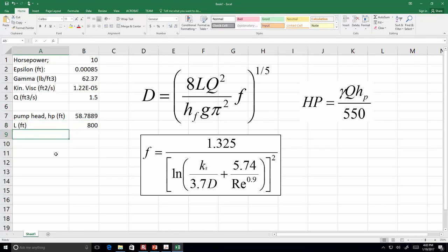All right, so we can calculate the F value the first time around using the Swamee-Jain equation because we've got the, I guess I haven't typed in the diameter yet. The pipe diameter in feet here is unknown. So we have to start with a guess. And what you can do when we have to start with a guess of the diameter in order to calculate the first F value, there's a number of strategies there.